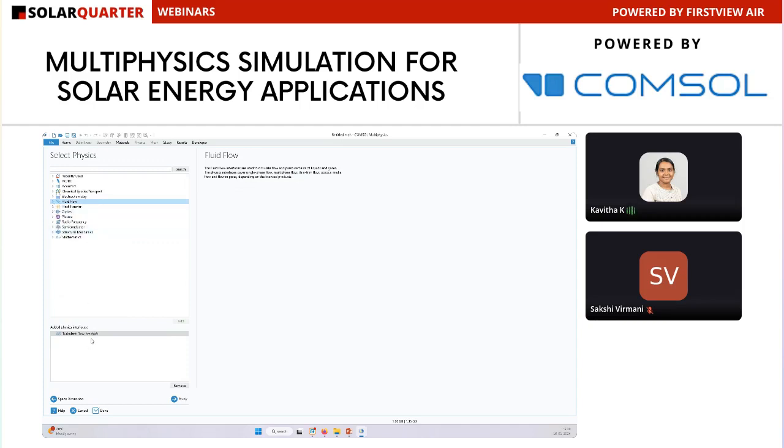So as I told, you can solve for single physics or multiple physics, n number of multiple physics together to have a coupled simulation, and your coupling can be unidirectional or fully coupled. So here it is a coupled multiphysics simulation. The wind load is going to apply stress on your solar panel, so we also need to include the stress effects.